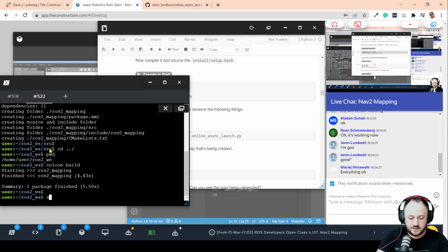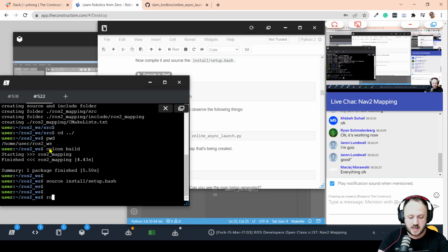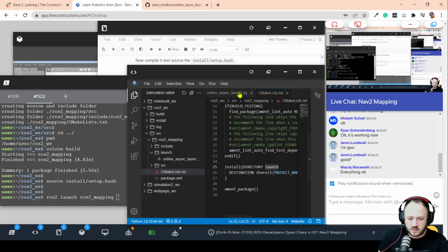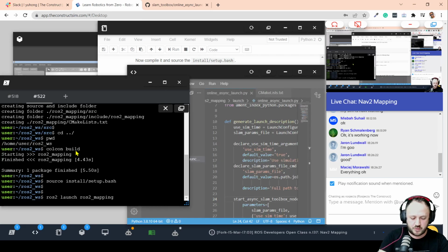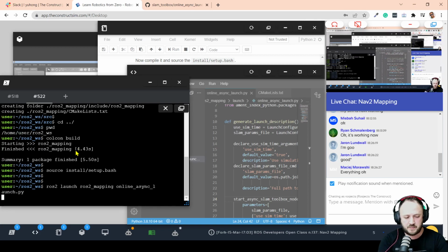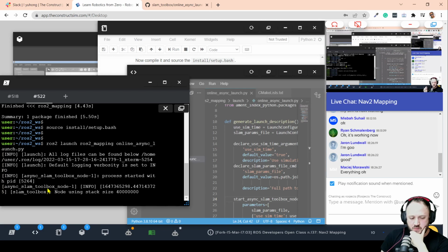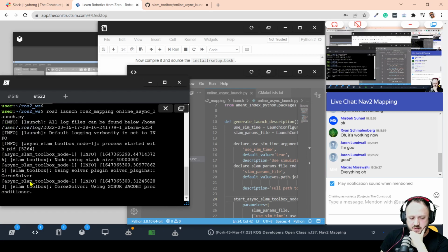All right, then let's source the workspace, and now let's run our launch file. So ROS2 launch, ROS2 mapping, and what was the name? Online async launch. Okay, online async launch.py. There we go. All right, so we have our launch file running. It has started here the async slam toolbox node.